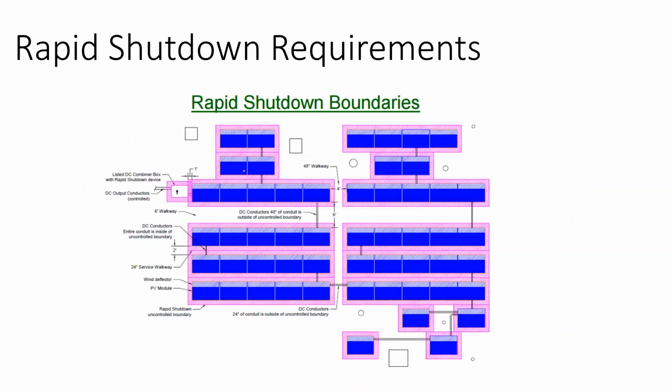And so, either you're doing microinverters and putting a little box behind every single module on the rooftop that, when there's a power outage, can kill the power right at the module itself, or you use a rapid shutdown combiner box. Even if you're actually not combining the circuits together, there are boxes on the market now that you put next to your array or under your array that you run all the circuits back into, and you kill the power at the box.